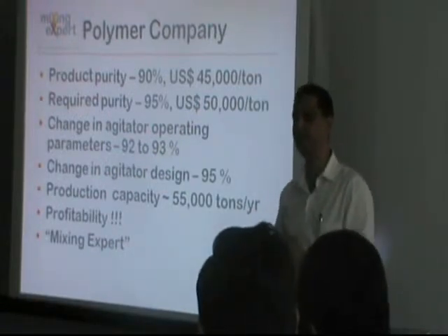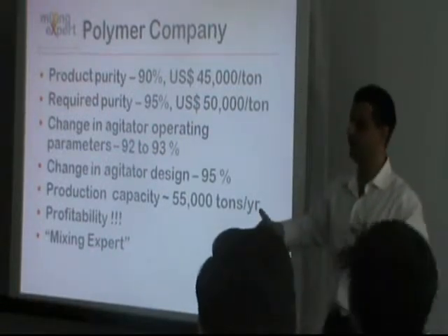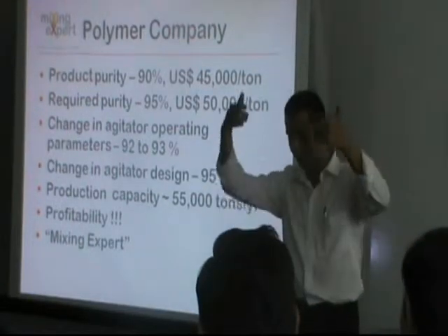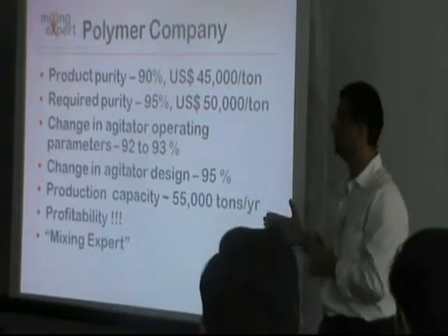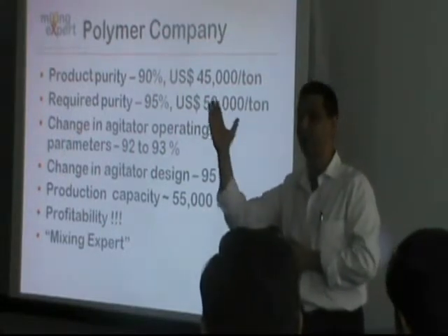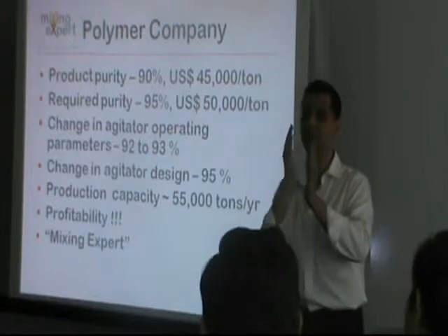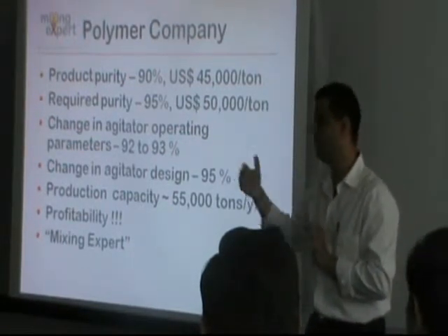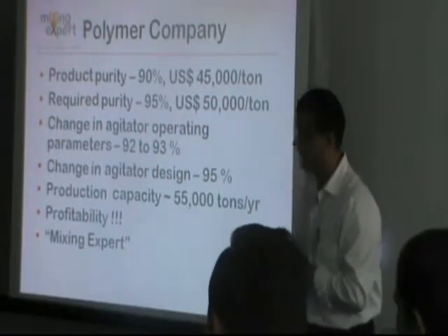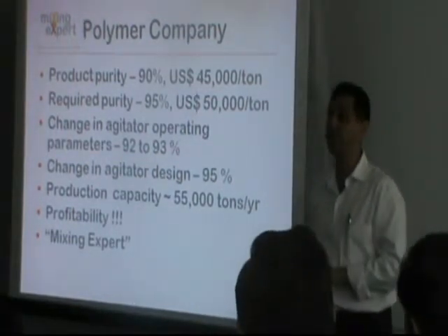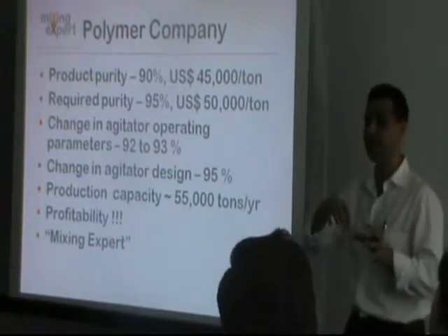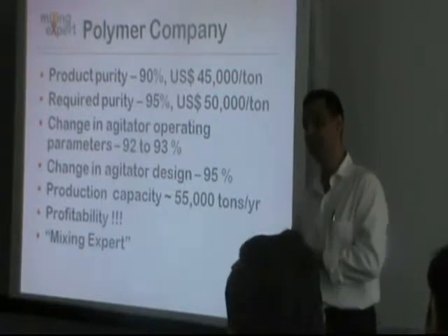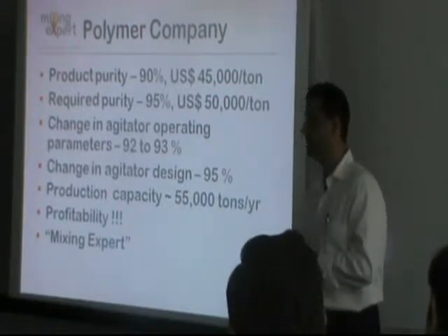Now, in this case, conventionally the baffles are wall baffles. They would be welded onto the vessel, and there would be flats. Now, in this case, because it was a polymer application, they did not want any corners. They did not want any deposition of the material in the corners, because that would not get washed out along with the batch. That would remain, and that would probably be a contamination in the next batch. So the conventional baffles wouldn't work. So we had to design baffles with low shear, which did not have a corner. And we then came up with the concept of pipe baffles.